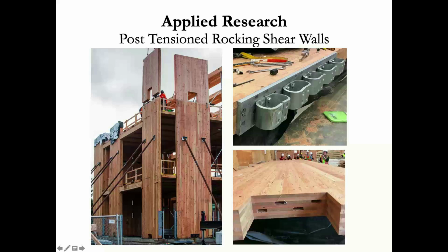That are very tricky to fabricate. So good on you guys at D.R. Johnson. But essentially, in an earthquake, there's a point here where the panels are attached, but they can rock on their edges, on their corners, but be pulled back to the central point after the seismic event. And these connectors at the side are intended to flex and deform, and will have to be replaced. But the idea being, these are fairly inexpensive items to replace compared to the building itself being unoccupiable after the seismic event.